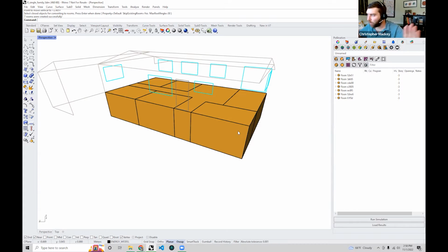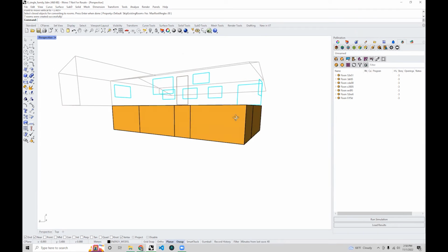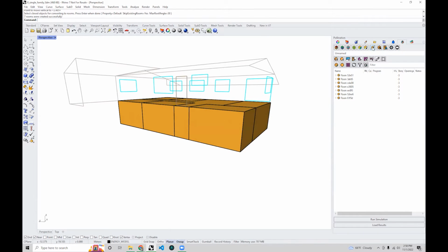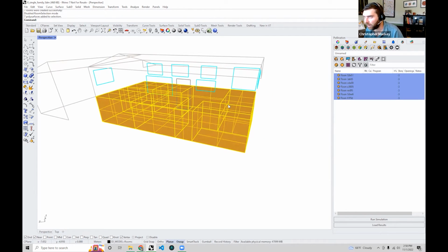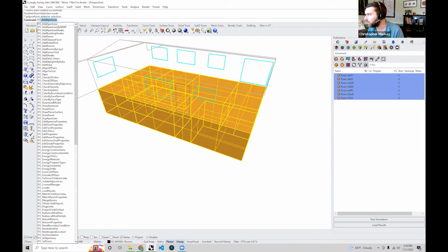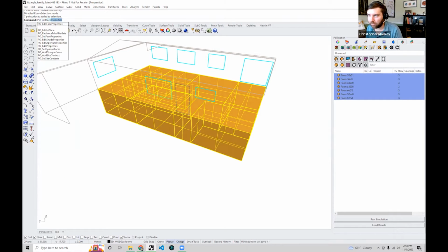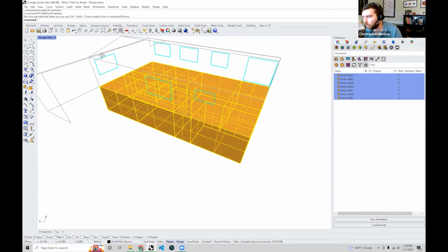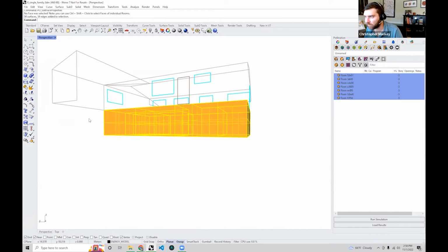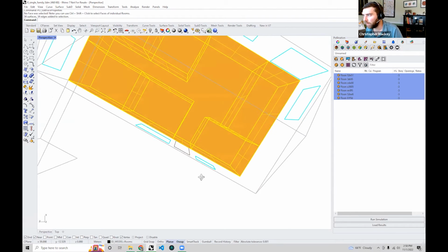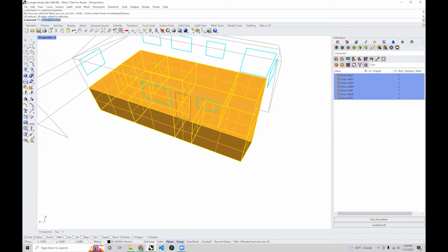You could always go through and change it. So if I wanted, I could probably turn off room selection, maybe select all these faces, and then I can go to PO, edit face properties, and I can change the individual boundary conditions of those faces. Or it says no faces. You have to do Control-Shift to select the face. If you do Control-Shift and click on one.